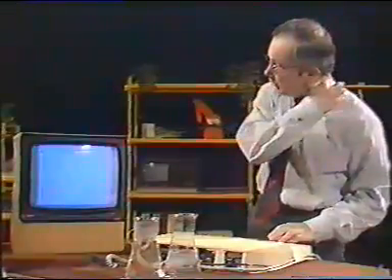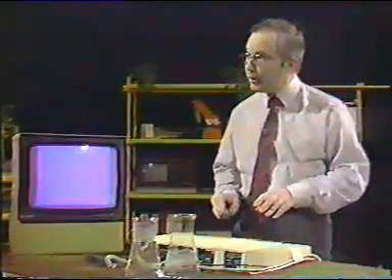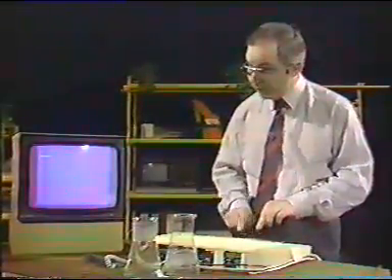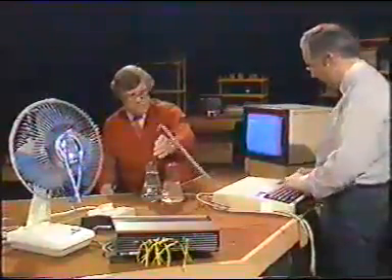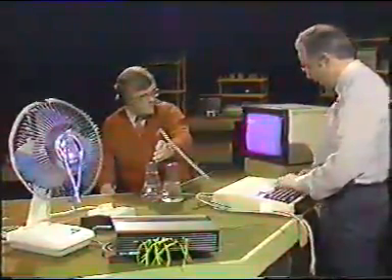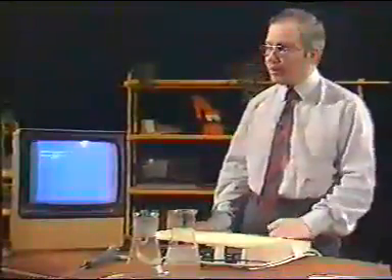In fact, we could stop the program running and I could tell it to print, could you put it in the ice? Print ADVAL 1, which will ask it to print the number that it's getting in from that input at the moment. And presumably a higher value if you put it in the hot water. That's right. So if we now ask it to print ADVAL 1 again, you'll get a much higher value because there's a much higher voltage being produced by the temperature probe. So that gets it in.